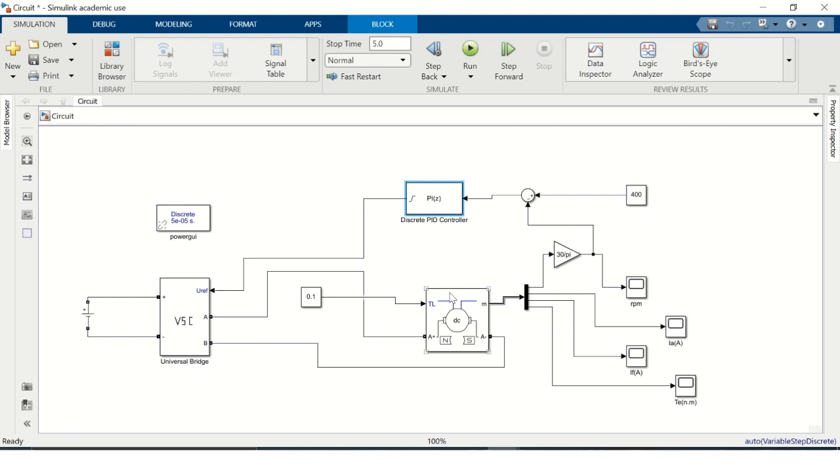Based on our design, the output of the DC motor is being measured and fed back to the PID controller for error correction until the desired value is achieved. So the speed of the shaft will be measured and fed back into the system to reduce the error. So we decide to use this because it is suitable for our circuit.